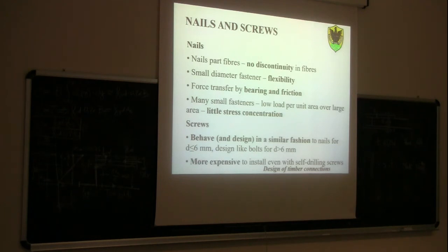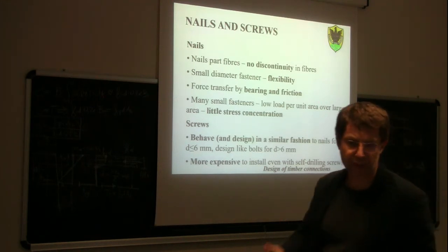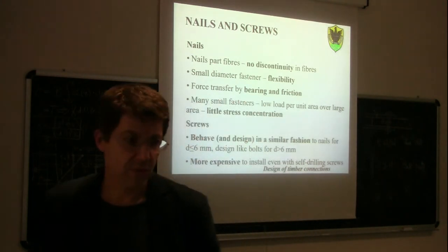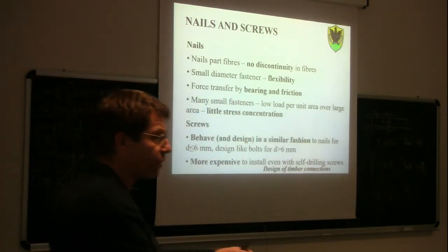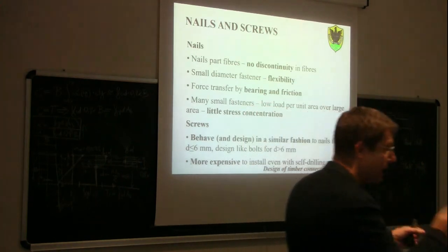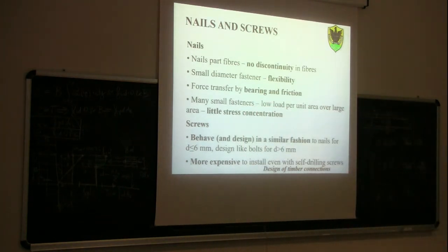In general, screws are more expensive to install because usually the nails are shot into the timber. So usually, when we use a nail connection, we don't go there with a hammer like in the old days. We have a kind of nail gun. With this gun, you basically shoot the nail, so it's very fast, of course. You need to be a bit careful with this kind of nail gun because it's a light weapon, you can imagine.